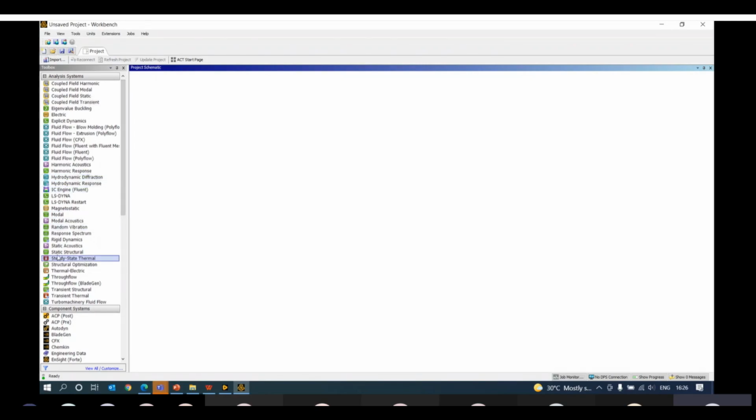Say for performing any problem, let me consider I'm working with a structural one. So for material, if I want to define, engineering data is there. Then to create geometry or import geometry, I can click on it and work with further meshing, connections and doing the setup and solution I'm looking for, and I can go for post processing.